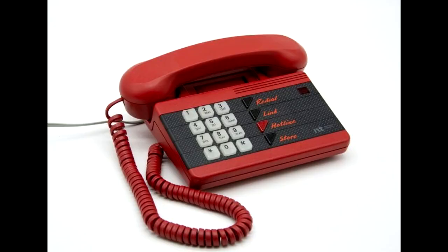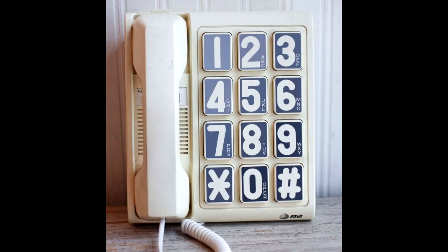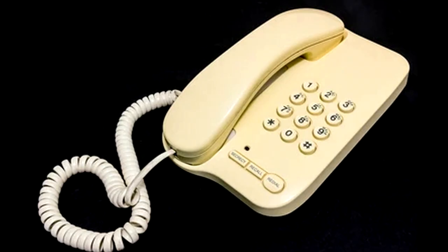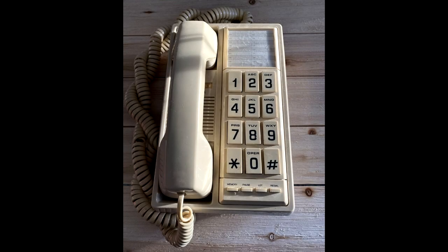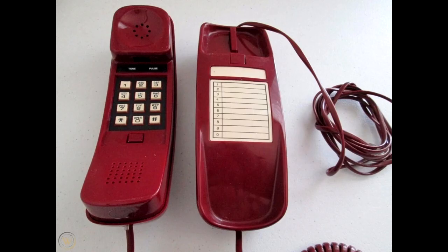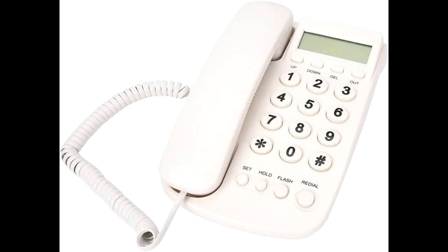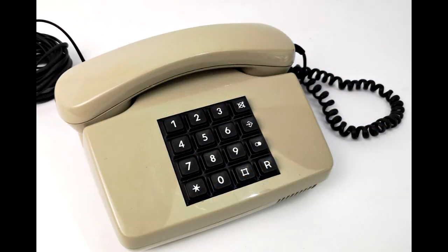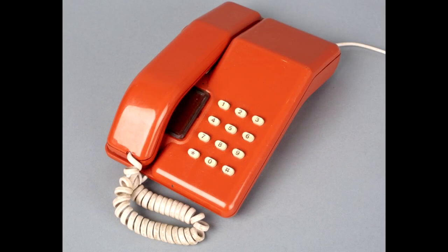In later phones made by independent manufacturers after 1984, many receiver speakers were more conventional. Test the speaker impedance with a multimeter. If it measures between 2 and 8 ohms, you probably won't need to replace the speaker with the one that came with the sound module. Look for a later model landline phone, and the chances are much better that you will be able to use the original phone speaker as it is.